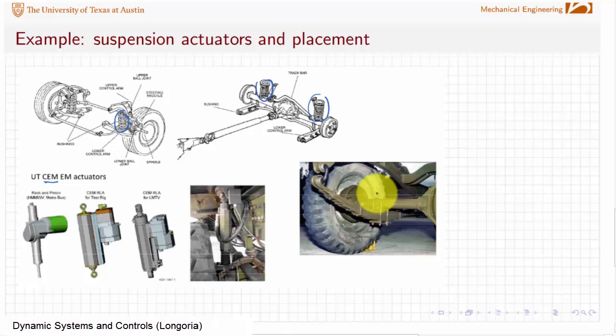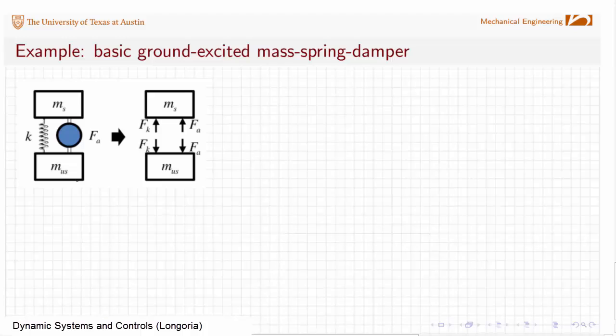I'm just showing this here to illustrate how you might put that into a solid axle as well. So now in schematic form, you can see your actuator, and I'm showing the actuator as a blue element here, creating an actuation force. If we do a little free body diagram, you can see that the actuator force is going to have the same velocity as your spring and damper if you want it. Typically, in an active suspension, you'll eliminate the damping element and incorporate any kind of passive damping into the control of your actuator.